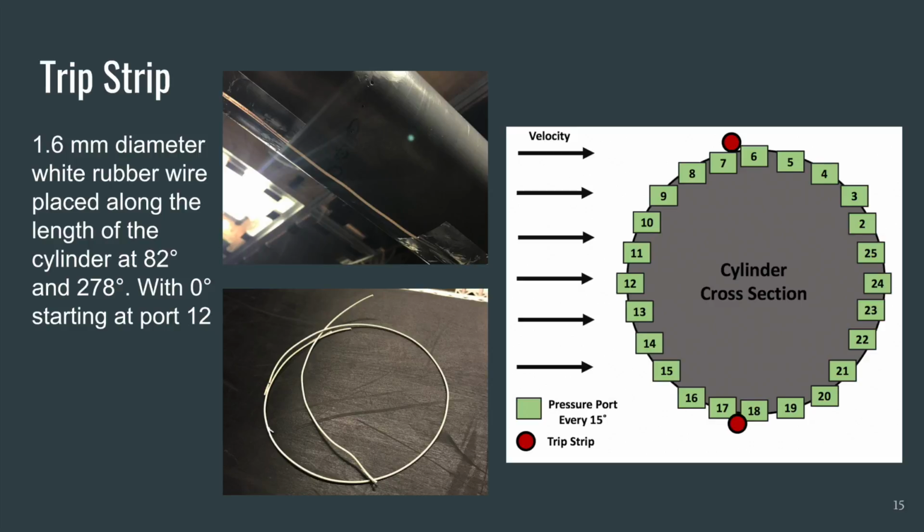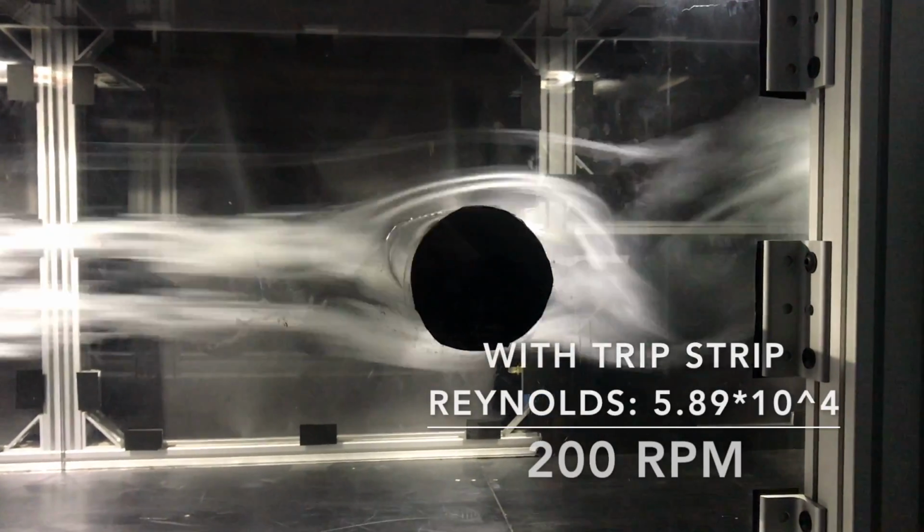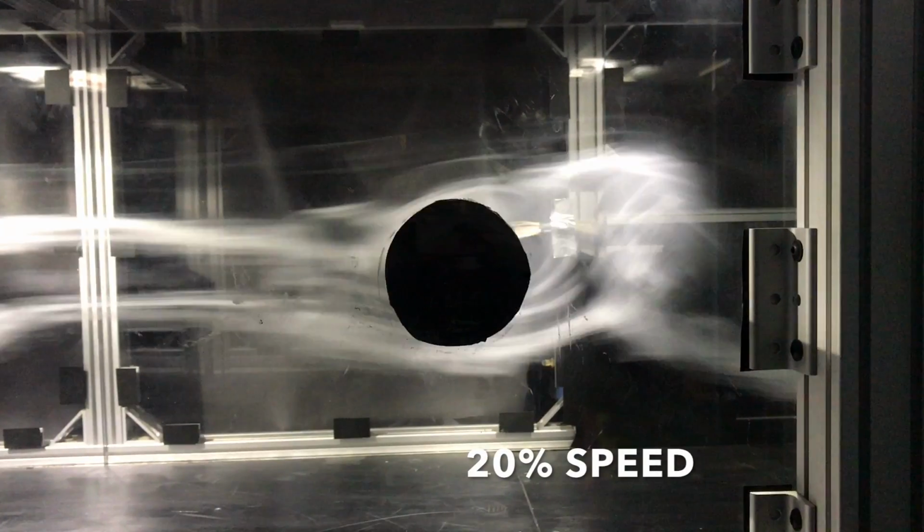Next, the team turned off the tunnel and attached the boundary layer trip and repeated the experiment. The trip strip was 1.5875 millimeter diameter rubber wire. The team taped it along the length of the cylinder at 82 and 278 degrees, with 0 degrees starting at port 12 going clockwise.